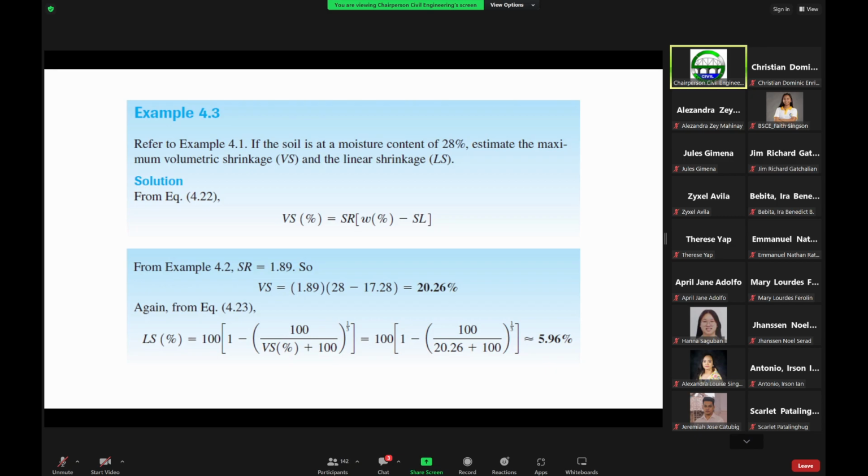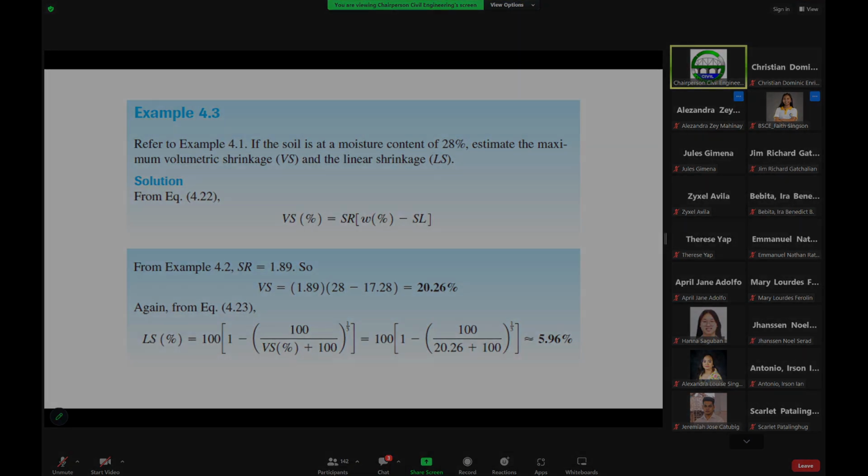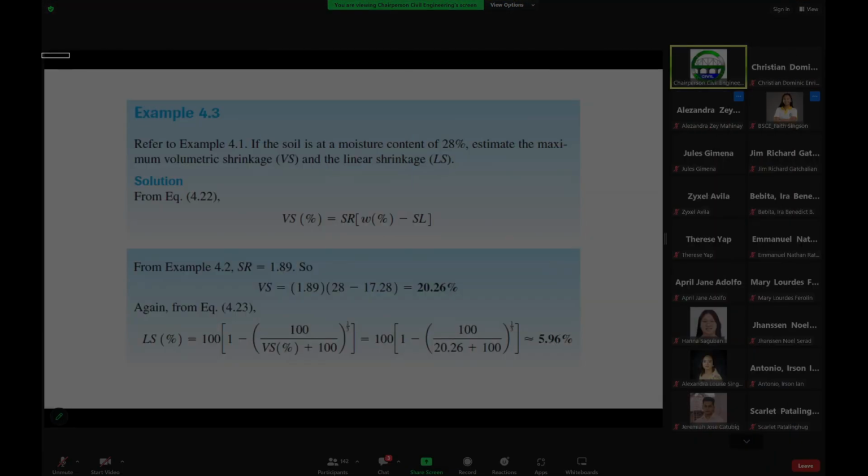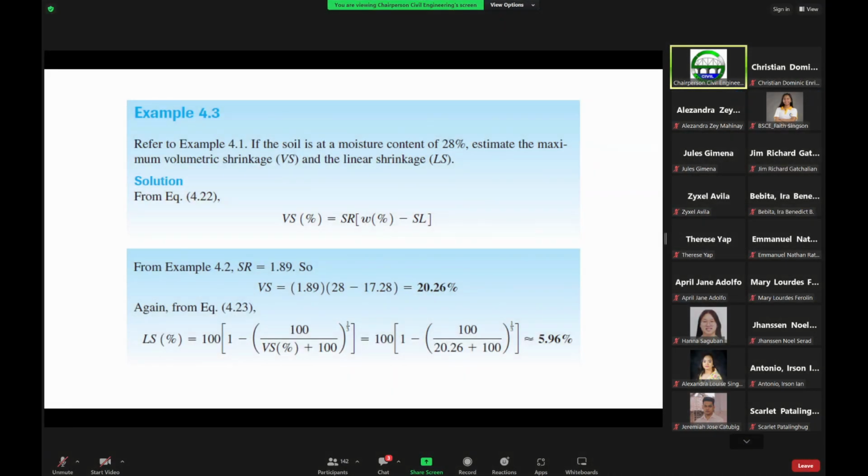The Atterberg limits, or the consistency. Then we also require the grain size test, to check for the grain size distribution curves, as well as the unit weights. And we also require the USCS classification, to be placed in the lab test results.